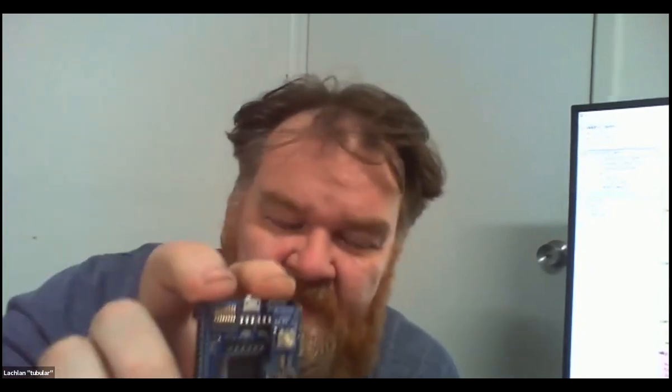Brian had 8 with manual pull ups and pull downs, and we've subsequently changed over to these rotary switches. Going forward, we'll probably put one of these little rotary switch footprints on almost every board we do, just so you've got the option of having multiple boards connected, busing them, right? Nice. Yeah, that helps.